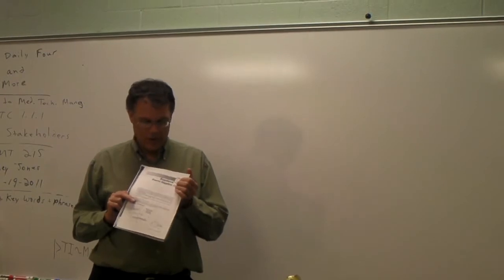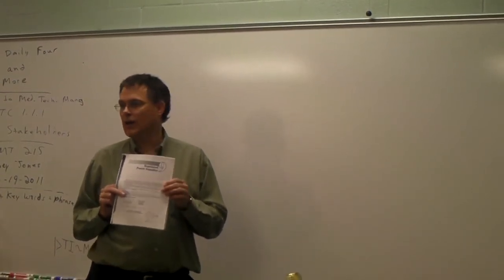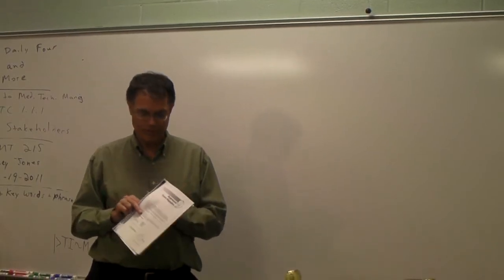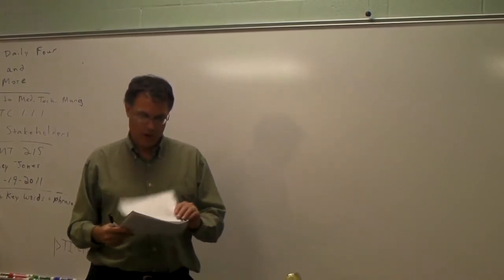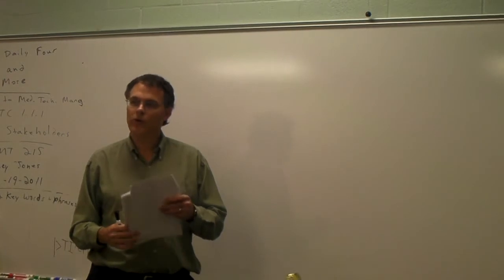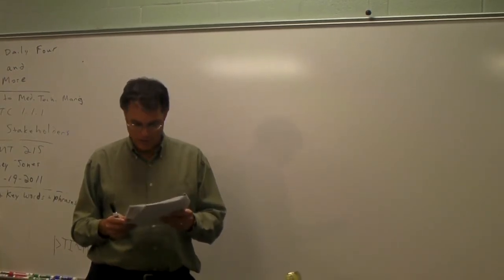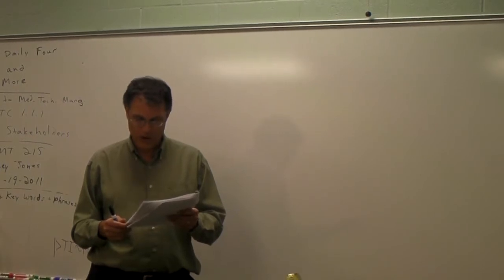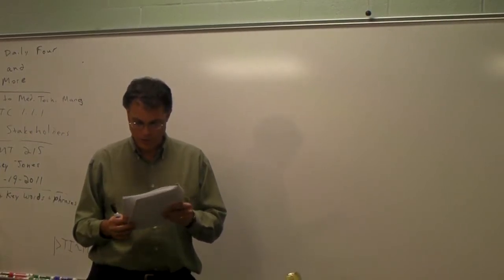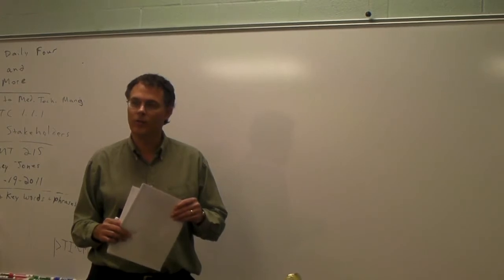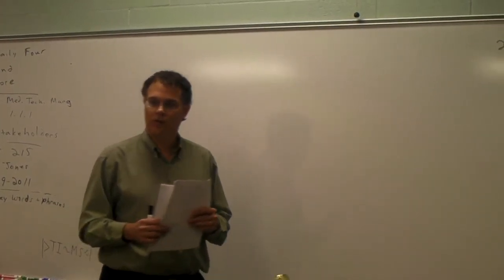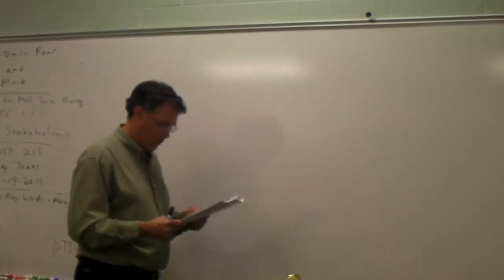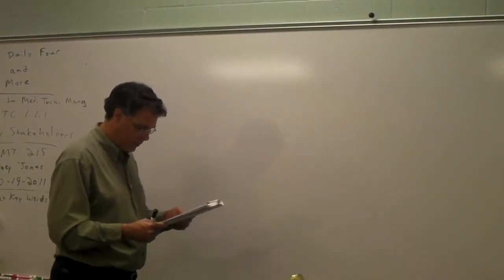Now, as I indicated previously, the Chapter 9 handout is going to be our primary resource that we'll utilize this morning. I'd like for you to turn to page 231 in that handout. At the bottom of page 231 is a circuit configuration for a zener diode and bipolar junction transistor voltage regulator that does not employ output sampling. So that will be our first circuit that we'll examine this morning, and I'm going to be drawing that same circuit as you see there at the bottom of page 231.